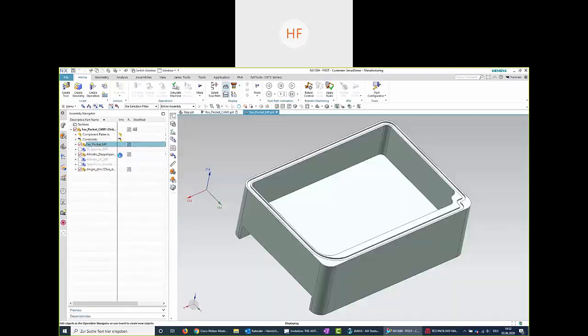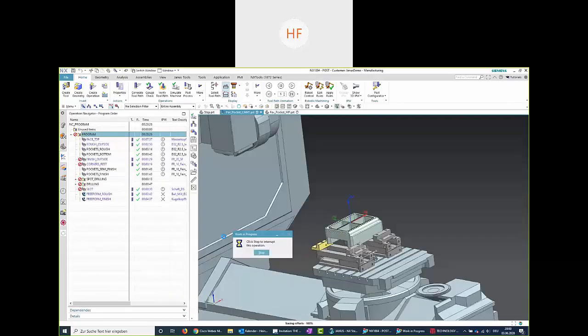The parts that I'm manufacturing can have any geometry. It doesn't matter if it's rectangular, it doesn't matter if it's a ball geometry whatsoever. The procedure for me is always the same. I'm just regenerating all the toolpaths that are already existing. If there are some new geometries that my reference part did not contain, I'm adding them by using those manufacturing sets. And for everything else, I'm using SpeedMill. For instance, the holes that we just have met in here.